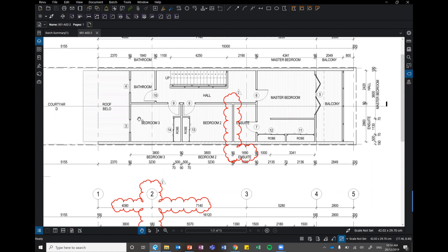I've tried it in Navisworks, but there's always little differences between them, a little 1 millimeter here or there, and Navisworks will find many, many differences. So we just want to find the general layout. If you're the builder, or maybe in a consulting company with access to Revit, of course, if you're loading in one file, you can isolate the walls, do a print, turn off that file, turn on the other consultant's file, isolate those walls and hit print. Then get Bluebeam to find the differences.